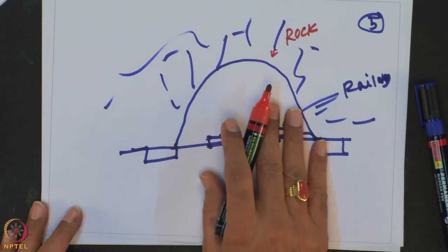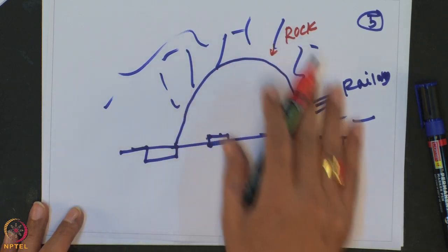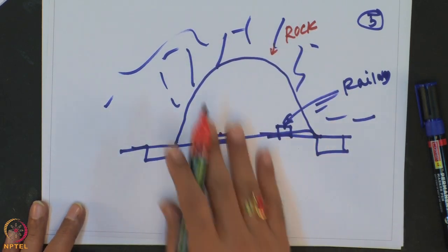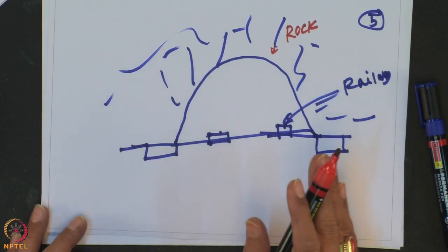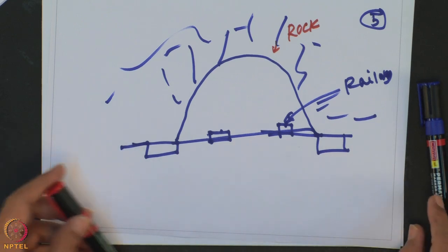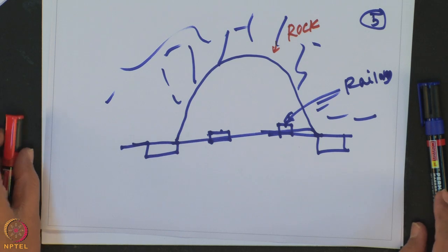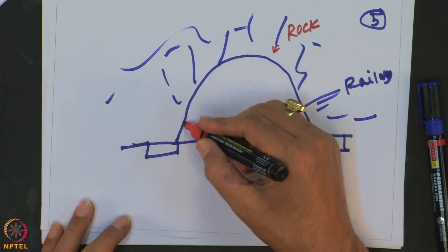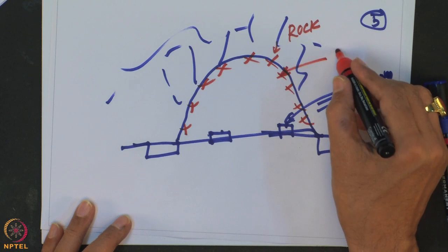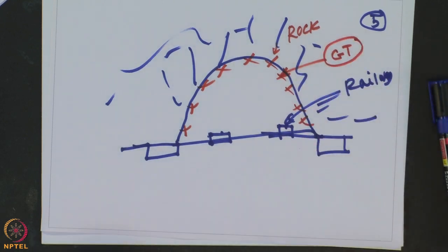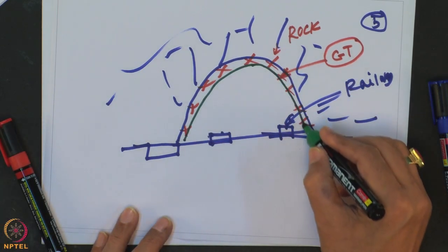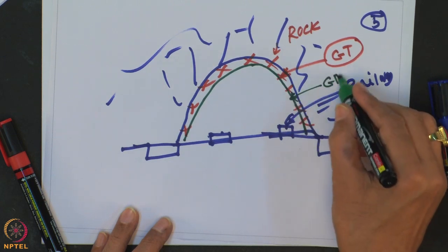Even for any tunnel work, even in a metro railway where there has been construction of a tunnel, you need proper means to control the seepage. This is very important. So, what is the role of the geosynthetic material? You can place one layer of non-woven geotextile material, this is the geotextile material GT. You can place another layer of geomembrane material here. Below this is the geomembrane material.